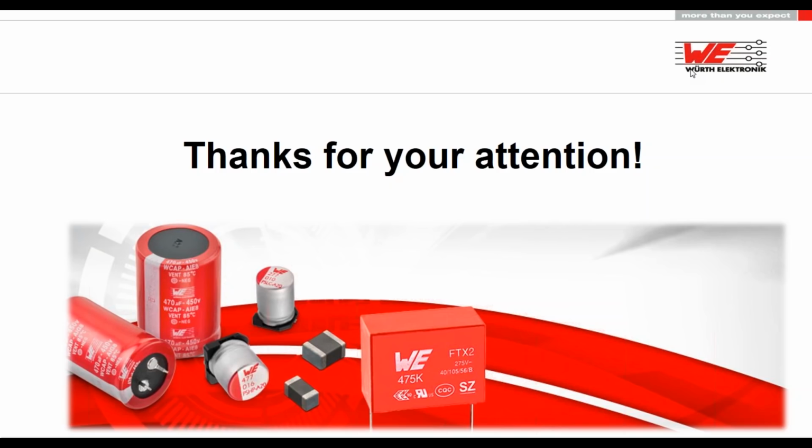So this means if you have, for example, 4 volt or let's say 6 volt, you shouldn't consider a 6.3 volt capacitor, because you're too close to the rated voltage, so the drop related to the DC bias effect is very, very strong. You should consider going for 10 volt or even 16 or 25 to have a proper capacitance yield out of the MLCC.